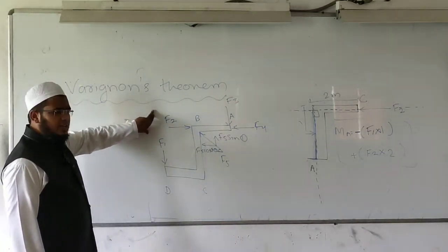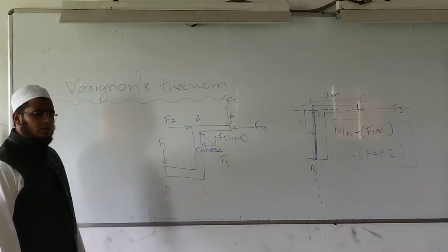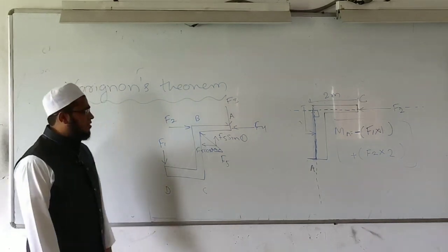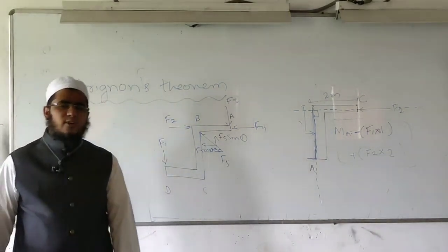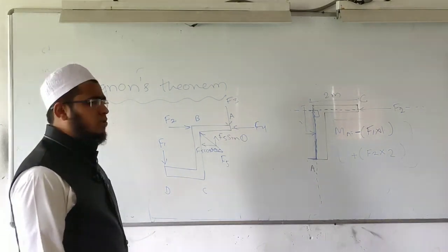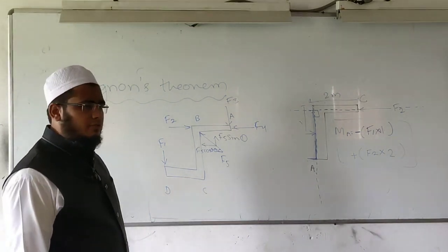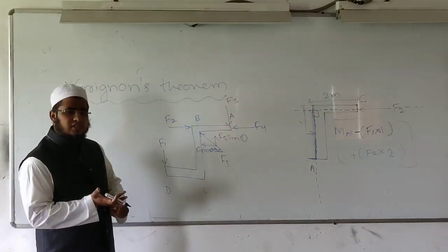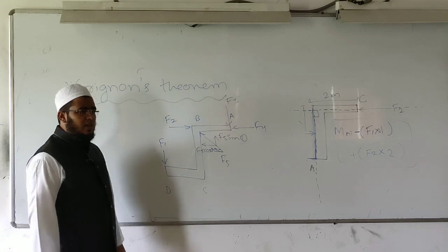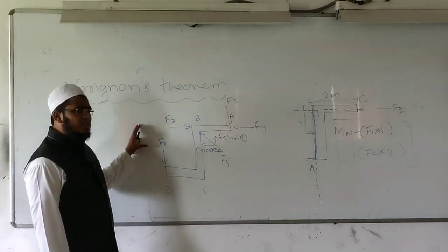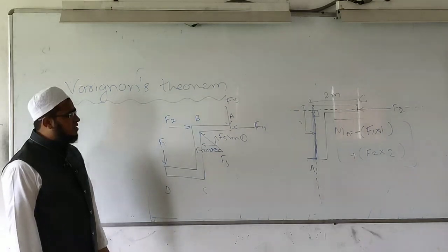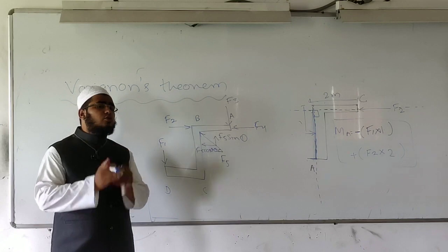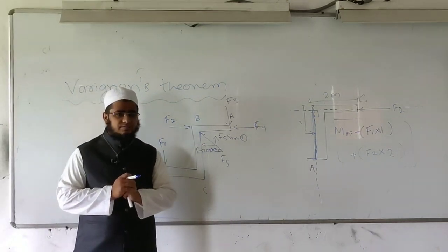Then I will find summation Fx, I will find summation Fy. Before that, resultant R equal to under root of summation Fx square plus summation Fy square. Then I will find the direction of resultant alpha equal to tan inverse of mod summation Fy divided by summation Fx. After this calculation, we know the magnitude of the resultant and the direction of the resultant. And from the sign of summation Fx and summation Fy, we can also decide in which quadrant that resultant is acting.